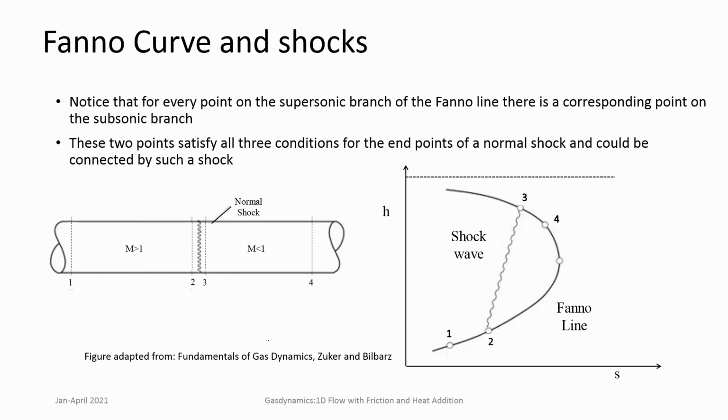The first thing that we have to understand here is, it is a 1D flow, and we know that in supersonic flows one can always expect shock waves, and in a 1D flow we look at normal shocks. Now the question we can ask here is, can a normal shock be present in a 1D duct with friction? So when there is a frictional flow happening, can there be a normal shock? If there is a normal shock, how will it get represented?